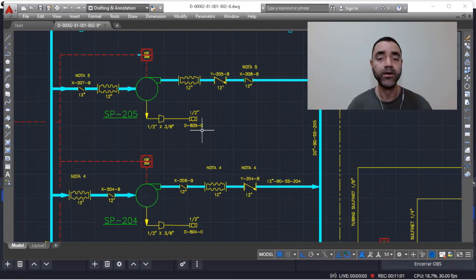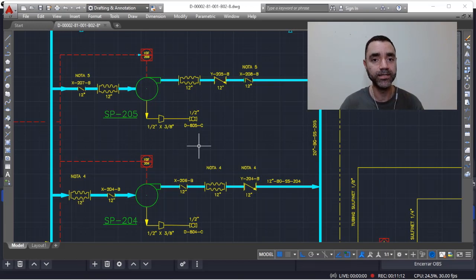Before starting the equipment again, especially if we are talking about too many days of maintenance or without operating the machine, or if the weather is very cold, before starting the equipment, you must open the drain valve to make sure that there is not any kind of liquid inside the rotating equipment, because the blower is designed to compress gas or vapors and not to compress liquid.